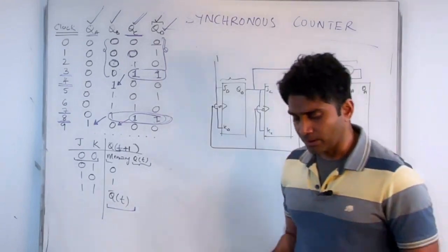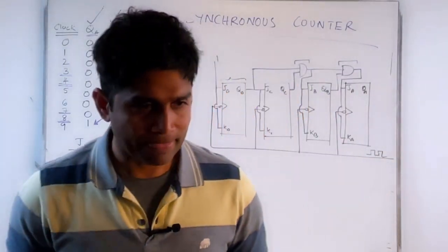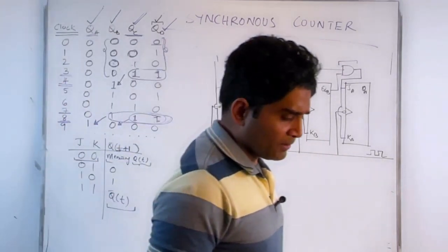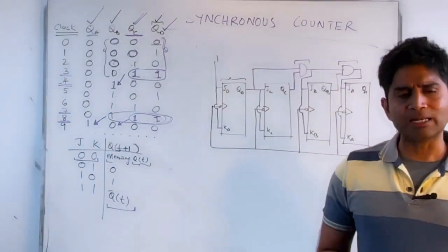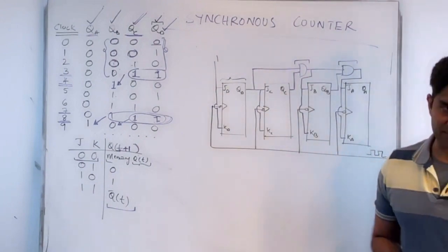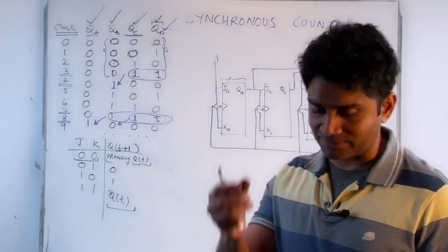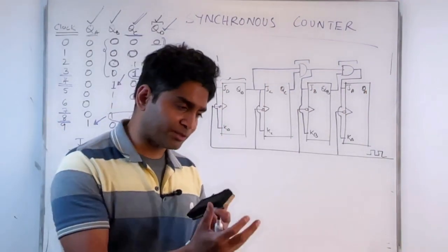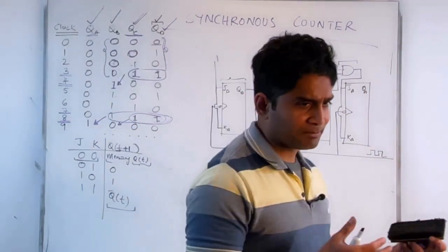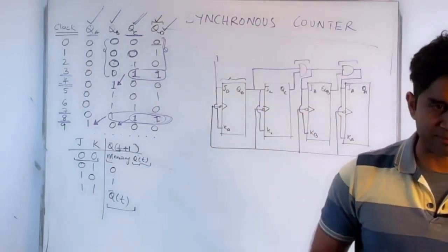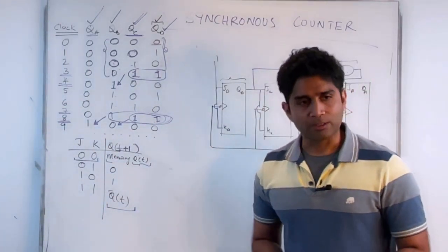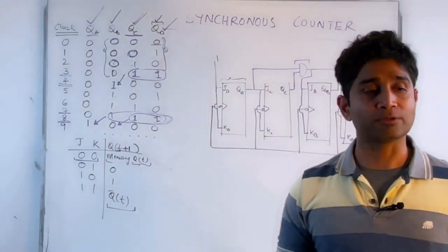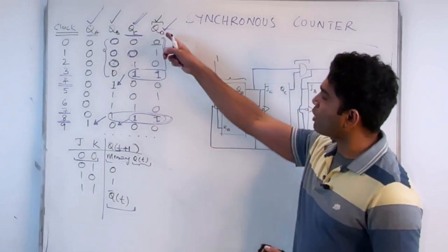How to design the synchronous counter? So now it's synchronized with the clock. Now, as you can see here, it's not very straightforward to design this. You need to really think about it. You need to examine the inputs and see how you can configure each stage to obtain those inputs. So it's not a very trivial thing, especially if you want to design something with a more complicated count pattern. Okay, because remember that your counter does not have to be counting this way.